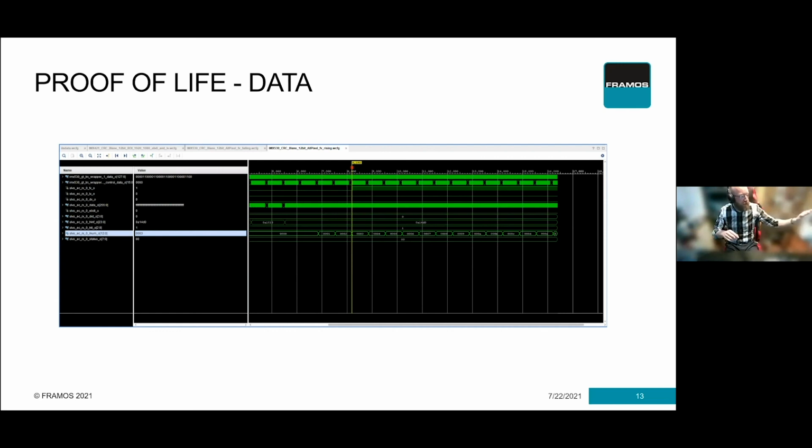If you bring these different light sources in, they don't necessarily all need to be calibrated, but they do need to offer a different color temperature of light, so you can see the performance of your system. Because you could make it look really, really good under LED light only, because you've tuned it just for LED light, and the system fails when there's an abundance of red light in it, because it typically always amplified that light, because the ISP didn't know any better.